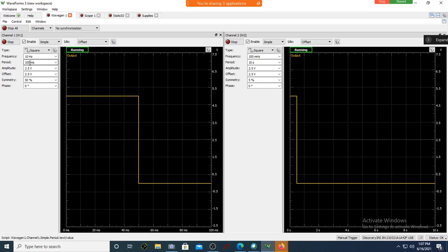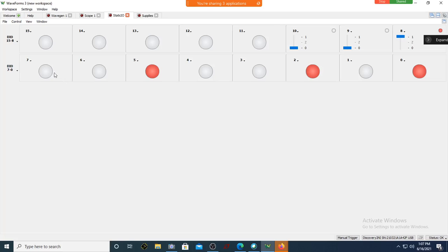It is 100 milliseconds into 64. It will be low for 6.4 seconds. For 6.4 seconds it will be low, then it goes high whenever your start of conversion goes. Now it is going low, so this will be low for 6.4 seconds. You can actually count that.